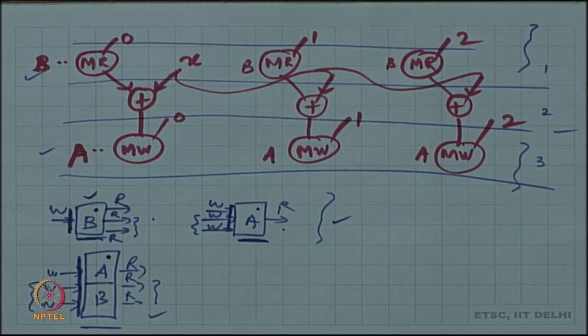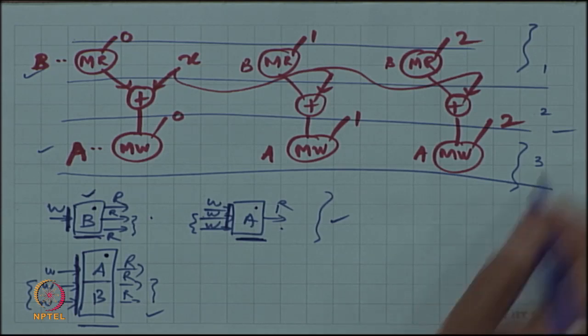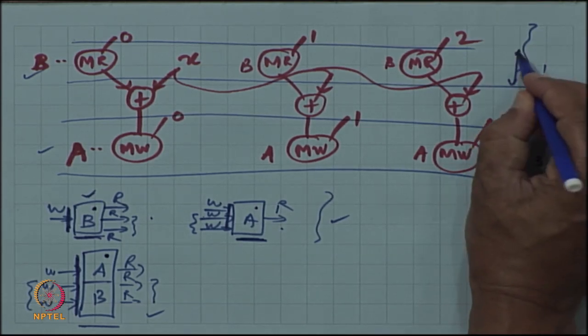So, by itself it is not obvious, but these are the parameters that affect the area related argument. There is also a delay related argument. The access time for the smaller memories is smaller than the access time for the larger memories. That is hard to argue about without looking at the context, because our context here is the clock period.